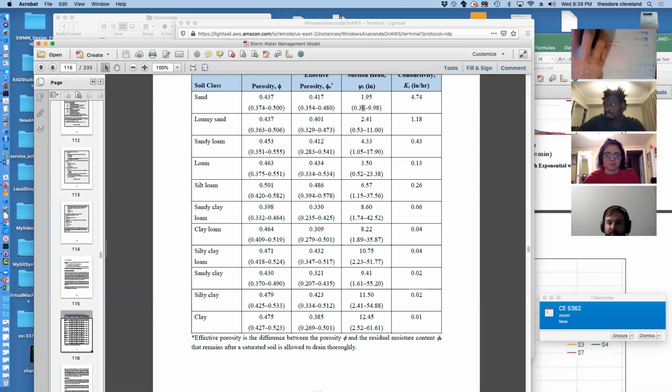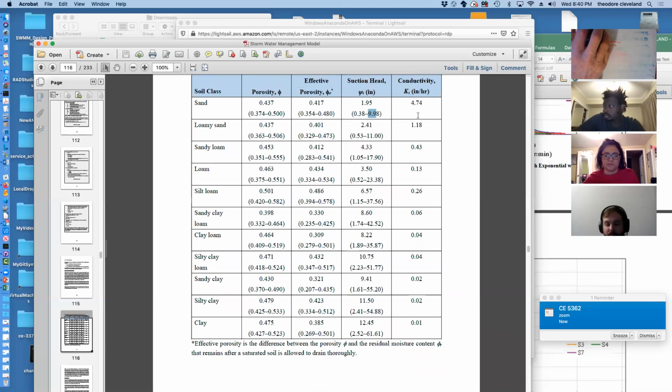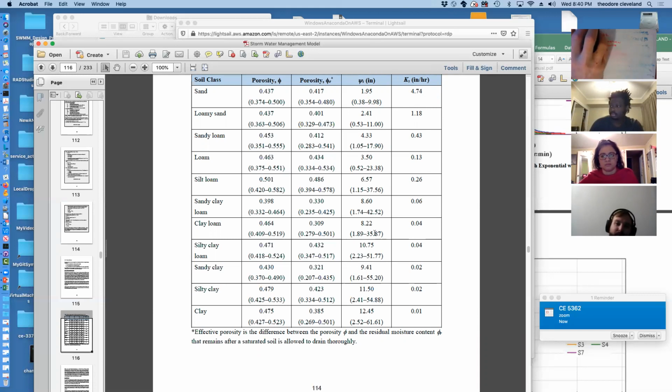And in the case of a suction head, I would tend to choose the higher value if indeed it was dry. And then the hydraulic conductivities, they're not presented with a range here, but I would tend to reduce my hydraulic conductivities in urban area to reflect that most urban soils, at least superficially, are unintentionally or intentionally compacted relative to a natural soil.